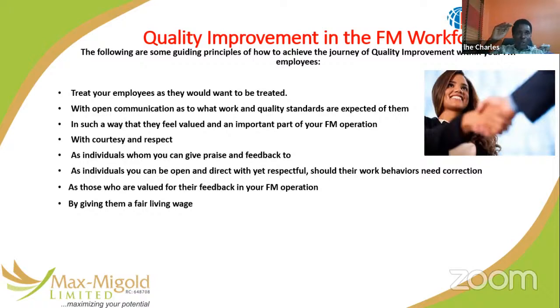That's where all the sockets must be installed, and every technician must understand that. Anything less than or higher than 1 meter from the floor is a non-conformance, and the clients will never be happy with that, they always frown at it.